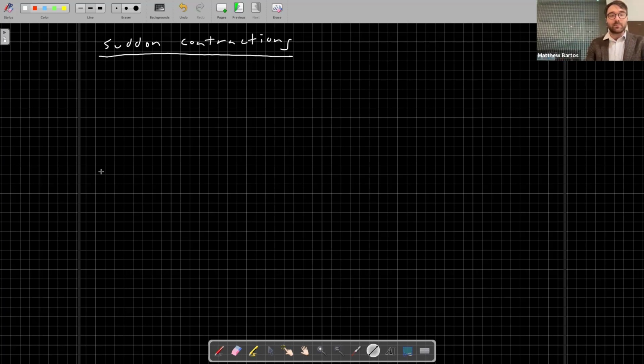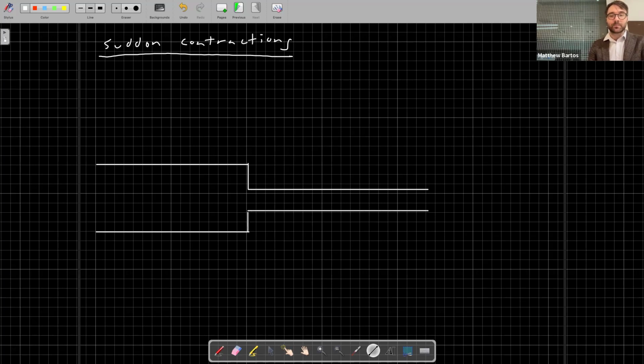This happens when a larger pipe transitions into a smaller pipe. So this is pretty common in water distribution networks, other types of plumbing. You might have a large water main transitioning into a service pipe, for instance. We'll get something that looks like this. And we can look at the streamlines. So as I mentioned before, you'll have streamlines that converge as they move from this larger pipe to the smaller pipe.